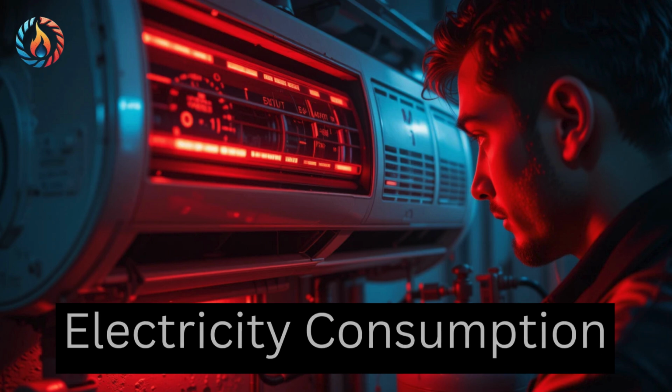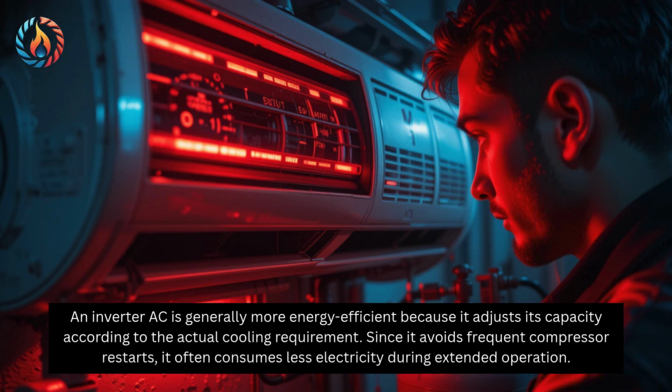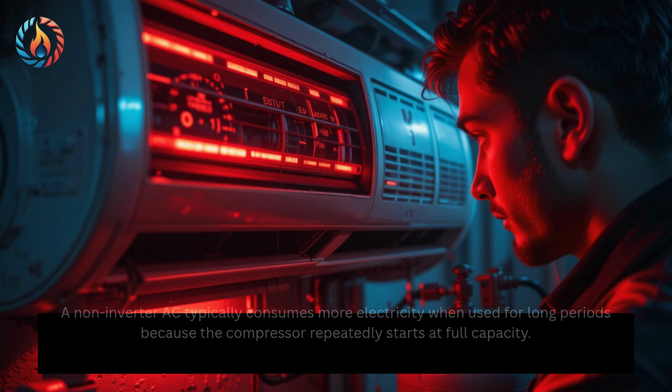Electricity consumption. One of the biggest differences between these two systems is energy consumption. An inverter AC is generally more energy efficient because it adjusts its capacity according to the actual cooling requirement. Since it avoids frequent compressor restarts, it often consumes less electricity during extended operation. A non-inverter AC typically consumes more electricity when used for long periods because the compressor repeatedly starts at full capacity.